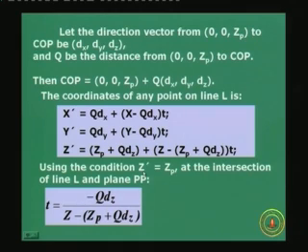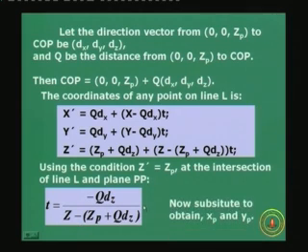We use that constraint and put it on the third equation, where z prime is equal to zp at that point, and that helps us to obtain the value of t. So, basically you substitute z prime equal to zp in the third equation, and then you use that to obtain the expression of t, which is given in the bottom left of this screen. This is the value of t at which the line L intersects the projection plane. Use this t value to substitute in the first two expressions of x prime, y prime, and what you get is nothing but the coordinates xp, yp.